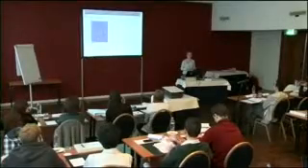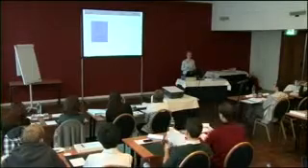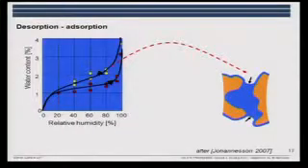Then I have shown you sorption isotherms. Now depending on how we measure, if we dry out the sample or if we wet the sample, with water vapor at increasing relative humidities, we'll get different sorption isotherms, as you see here. And when we dry out the sample, you can see it illustrated by this figure, that we have the drying out from these pore sizes. And we may have a larger pore in here, and that's what is giving this difference.